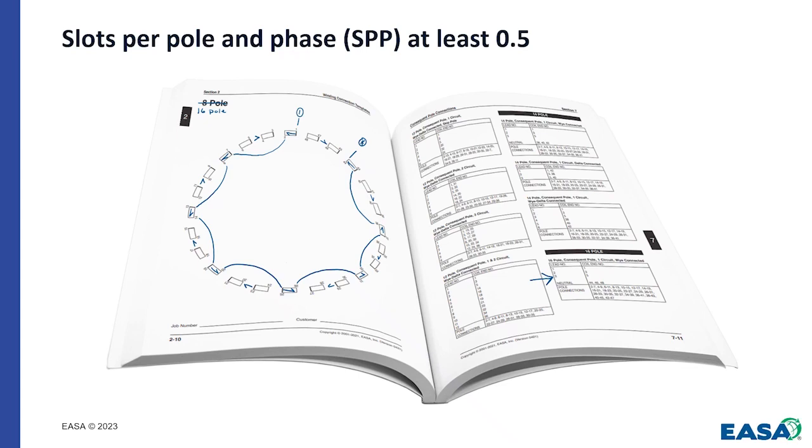It's a return path for our magnetic field. That magnetic field is preserved, and so what leaves a pole from the top has to return to the bottom. So when we count these poles, we see that we have 8 that are electrically wound groups of coils, and then we have consequent poles between to form the other 8 poles with opposite polarity. So we get our 16 pole machine.